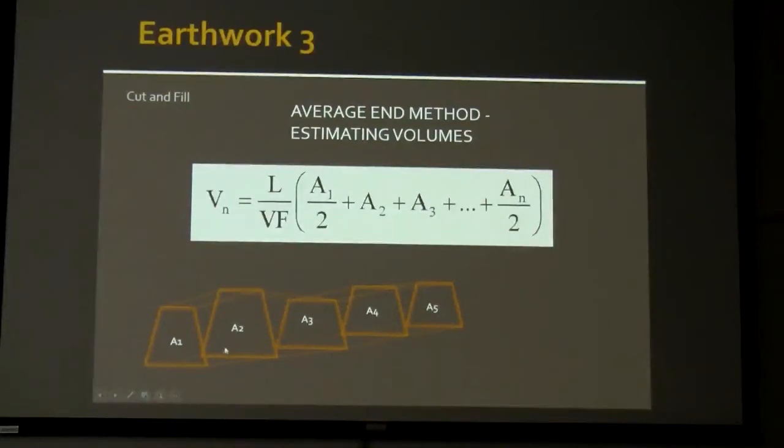We have 5 different cross-sectional areas that are based on using engineering judgment as to where we'll draw these lines. In this particular case, it looks like the lines from one cross-sectional area to the next are nice and straight. However, there will of course be some variations. We're estimating the volume here, and we're not actually getting an accurate measurement. We're estimating volumes using these formulas.